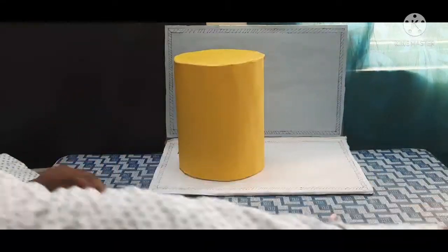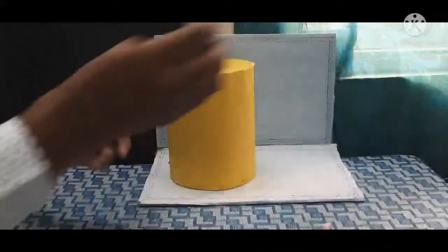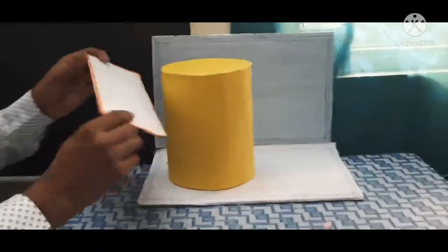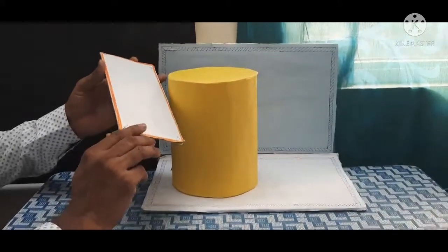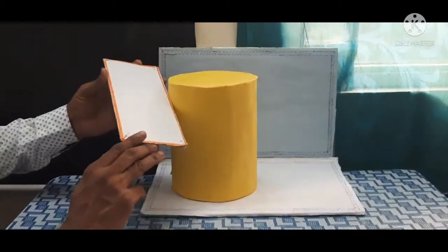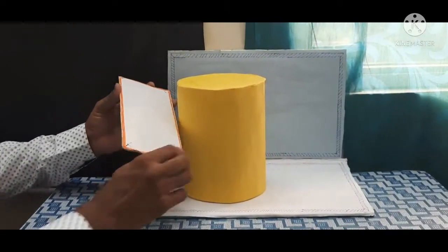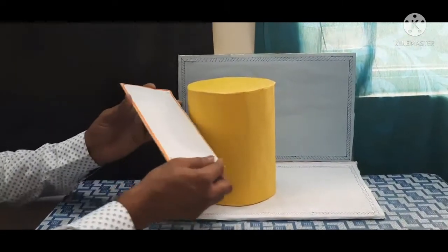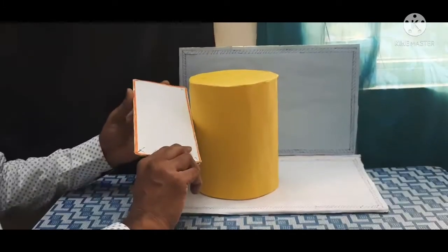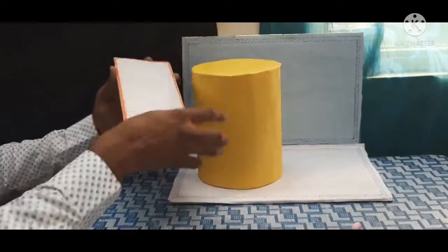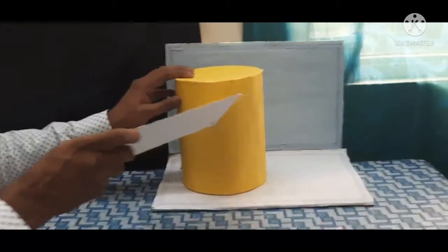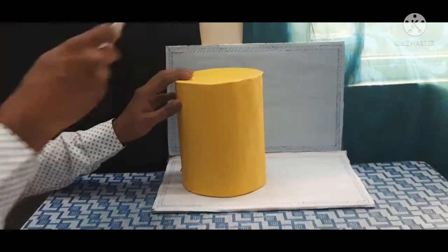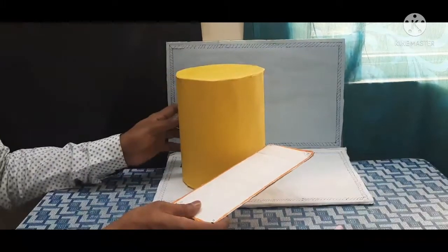You need to consider this. This is the rectangular cutting plane. I am going to cut this solid by keeping this angle of 35 degrees to HP, through this midpoint, slicing the solid like this. Then we are going to remove the top portion. You can cut in this direction or in this direction. We can remove this portion. Then we can draw the corresponding true shape of the section.